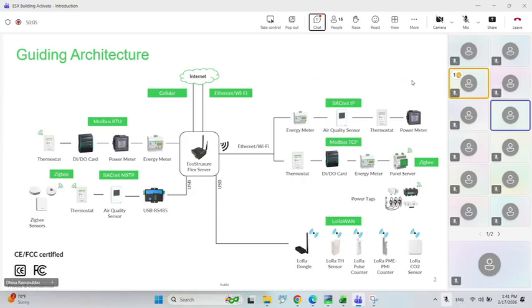No. Even for BACnet IP, for example, we are using our IP communication devices, RPC or ASP, and through that we are creating the devices in our commissioning portal. Whichever the device it is, we configure it as one device in the commissioning portal, either through the template or through the BACnet IP register. So the limitation is all protocols combined, a total of 50 devices: BACnet IP, BACnet MSTP, Modbus RTU, or LoRa.